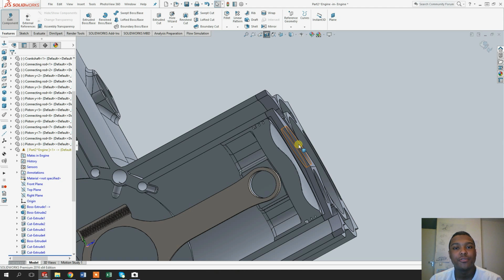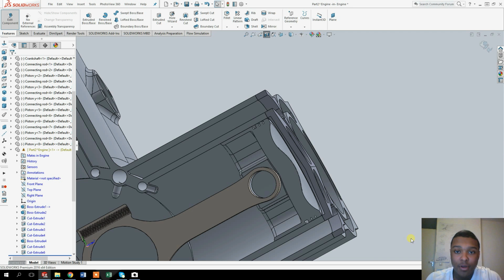These compression ratios were good with the type of petrol that we use around the world, and it makes sure that the temperature of the air mixture with fuel doesn't get to a certain pressure or temperature that would ignite the mixture prematurely. So that's also one of the risks with a higher compression ratio. With a higher compression ratio, the air to fuel mixture in the cylinder will also get to a way higher temperature and a way higher pressure, and this could cause premature ignition. So to prevent that from happening, you have to use a better fuel. So that's one of the disadvantages.